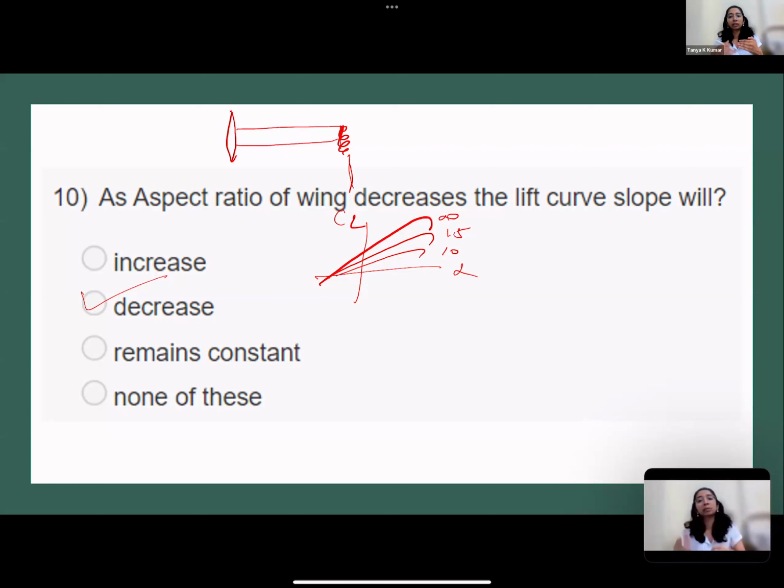So there is the boundary layer separation, there is drag over there. So there is a reduction in the lift that the airfoil could have generated. If it was of infinite span, then it would be generating that much lift. But since it is finite, there are vortices formed at the tip, which reduce the amount of lift generation. So for the same angle of attack, for an airfoil and for a wing, the lift will be different and it will be lesser for a wing, which is why the slope reduces. Okay.